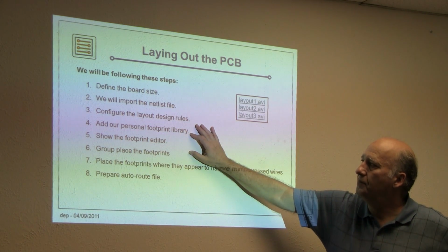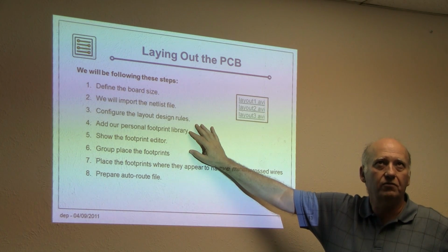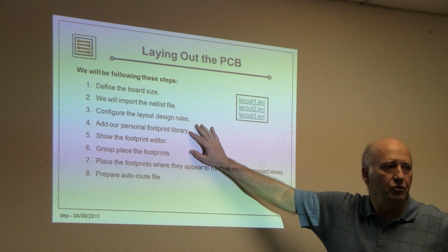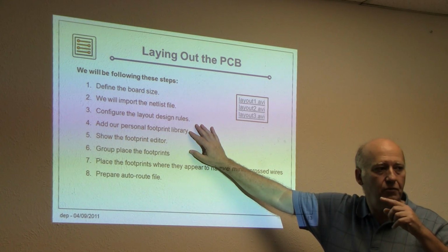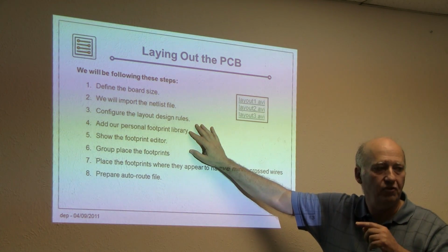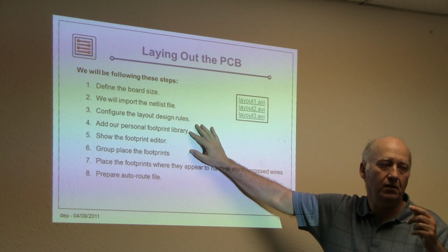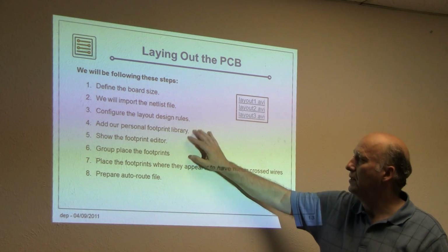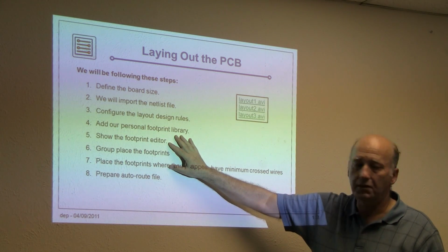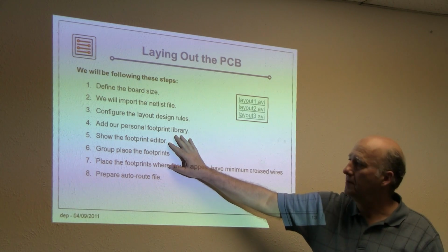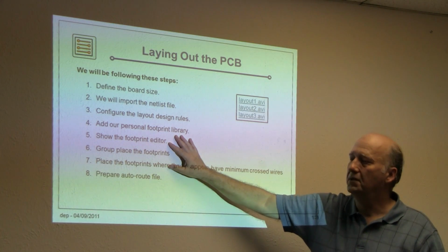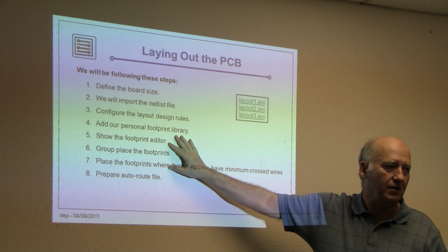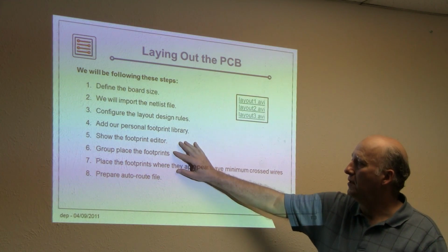Then, I don't think we do this in this particular example, but if you have your personal library, you have to bring it into the new PCB editor, just like you brought it into EESchema. You have to bring it in through the preferences menu. Okay, show the footprint under. No, we're not going to show that. It's very simple. I'll be willing to stay afterwards and show you how it works, but I don't think I did it.